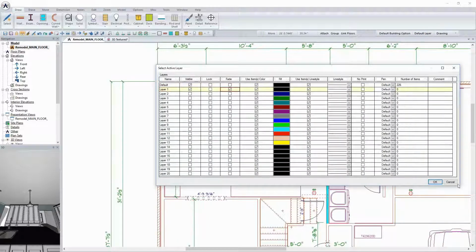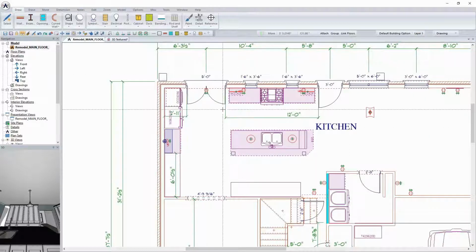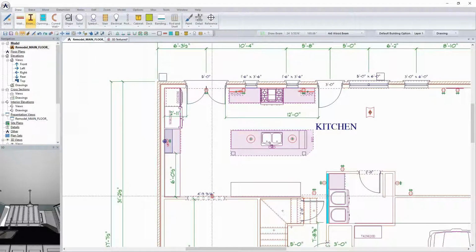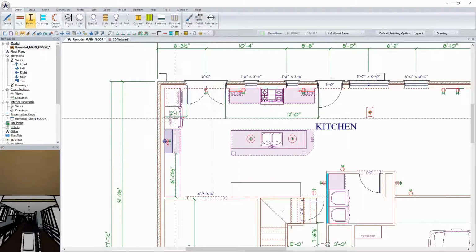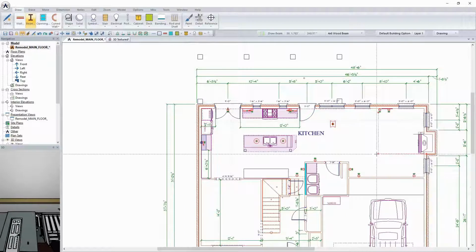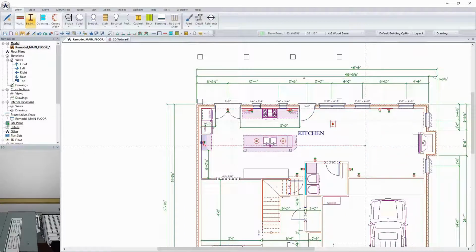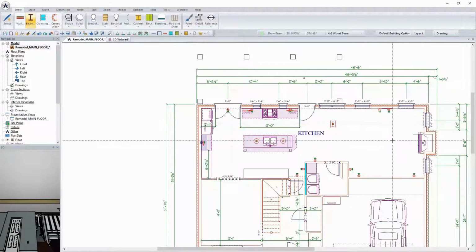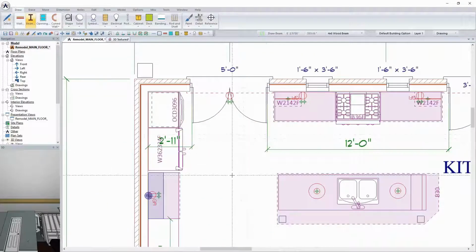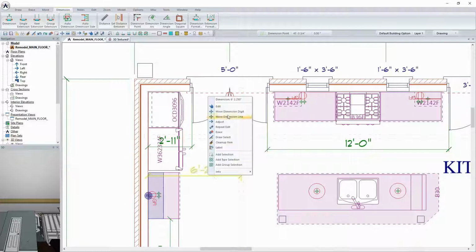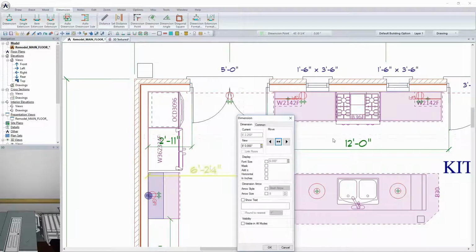I'm actually just going to draw in layer number 1 right now, the beams, but it could have been a building option and such. I'm going to draw a beam and pick this 4x6 wood beam, and draw one across this way. There was one that runs all the way across here, and as you're doing this, you'll be able to copy it or offset it. The fade feature that I put on there is why it seems so faded out. I'll pick the dimension and dimension point, draw it to that edge there, and edit this to make it 8 feet and hit to the right.